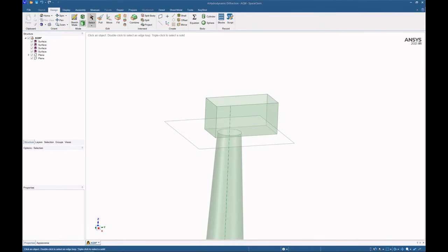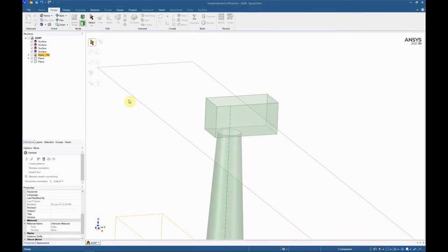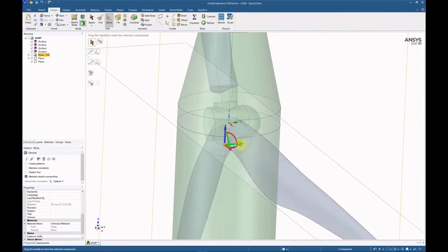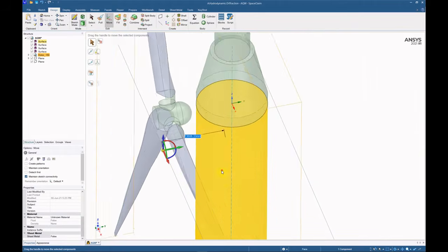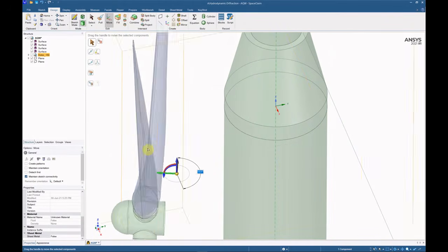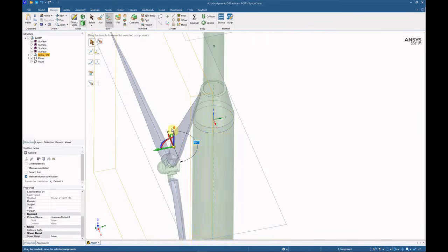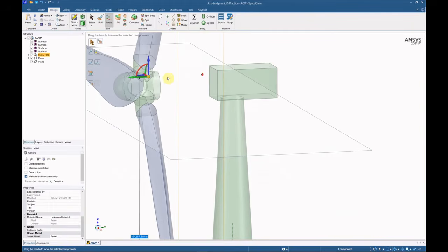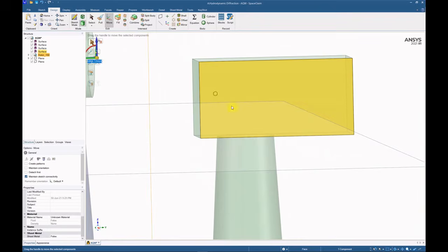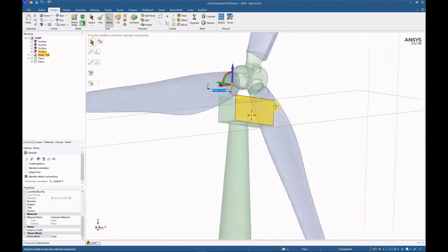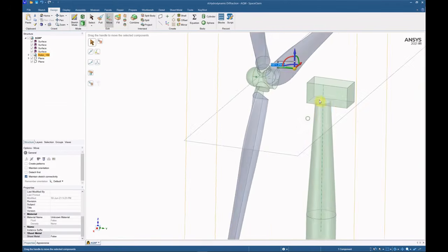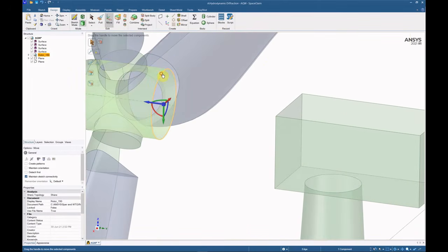It might be needed to do a cleanup or corrections in the imported CAD. After it is ready, import it in SpaceClaim, or drag and drop in the current model. Several move operations will be needed to position the rotor onto the nacelle front face center. Use the Move tool Center and Up To options to move it directly to a desired target easily.